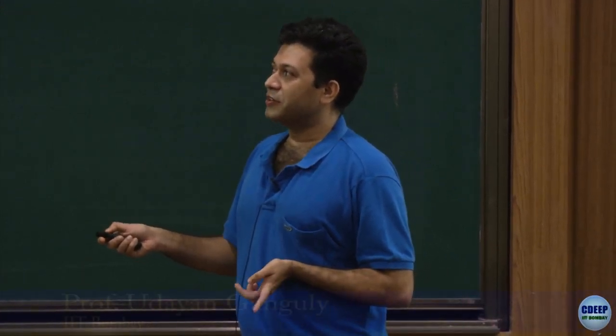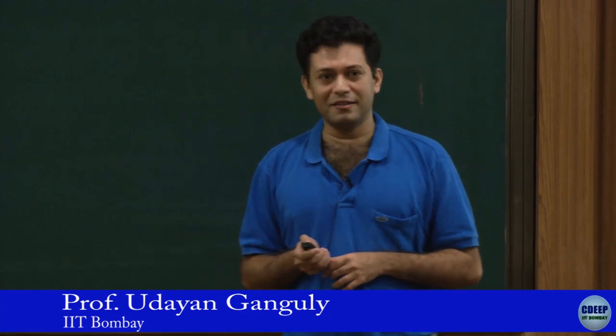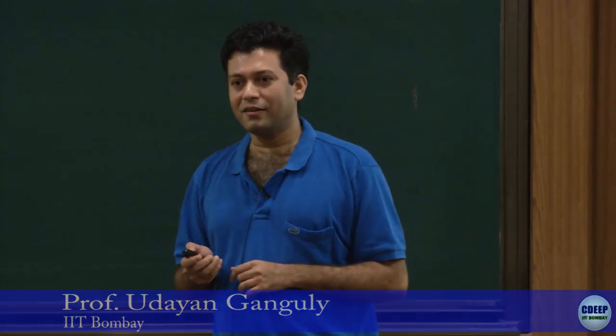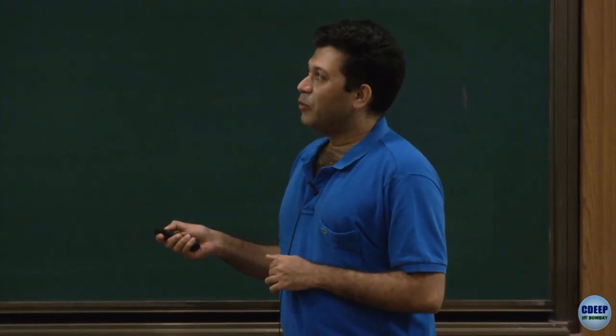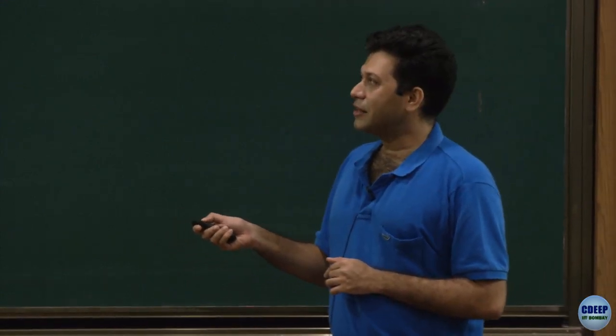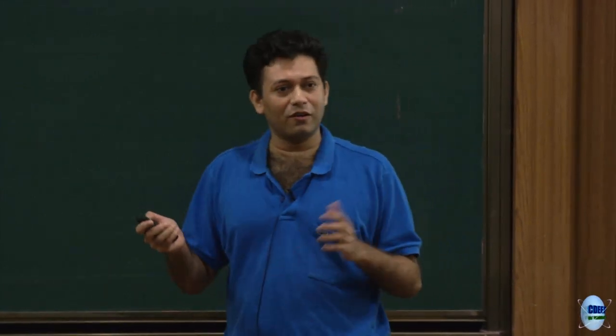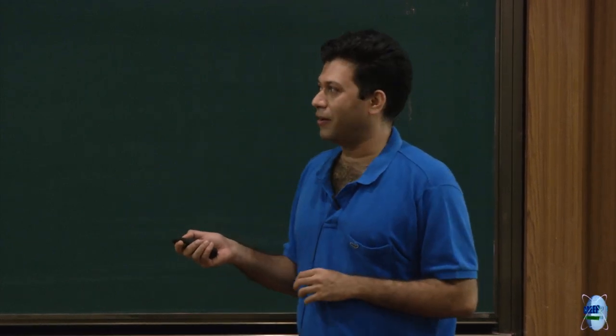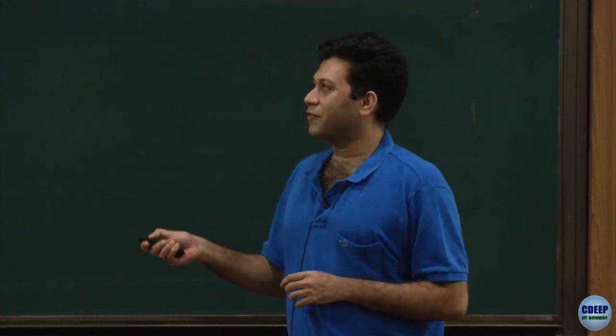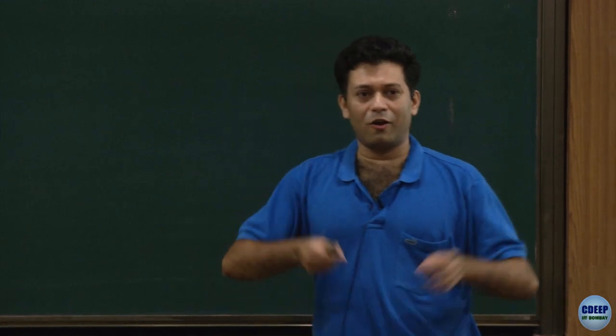What I'm doing is measuring resistance across this insulator, and this is an open circuit. If I blow the capacitor, I will get a filament of some sort which will create a short circuit. So this is a low resistance state. If I put a voltage across this, a lot of current will flow.